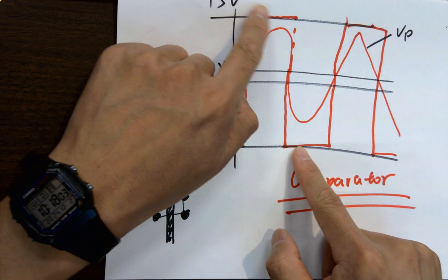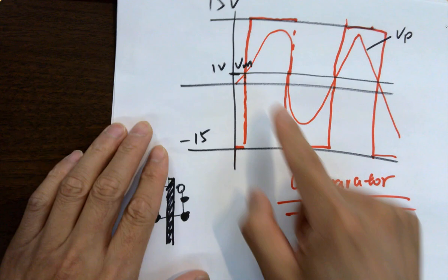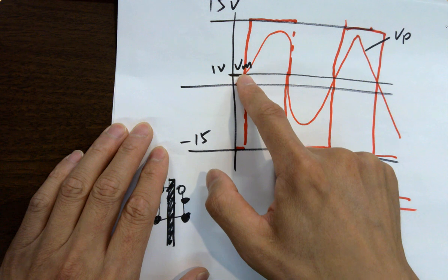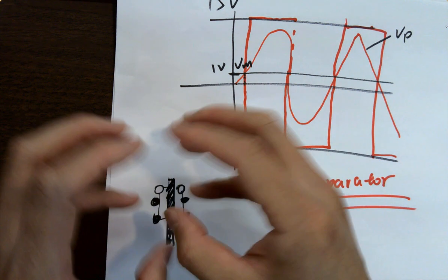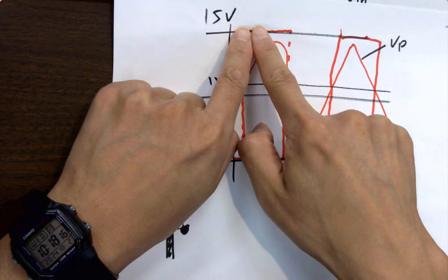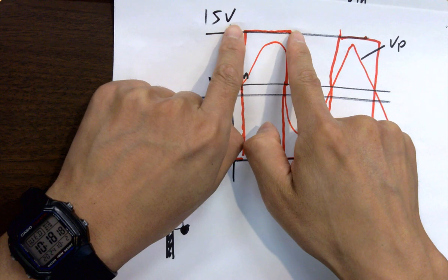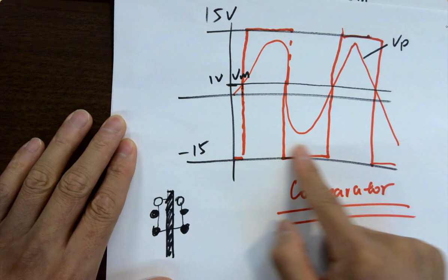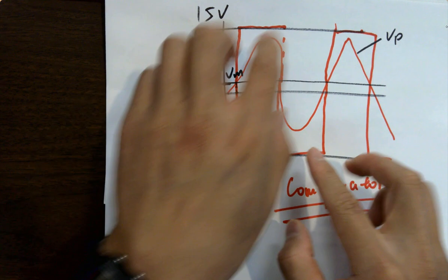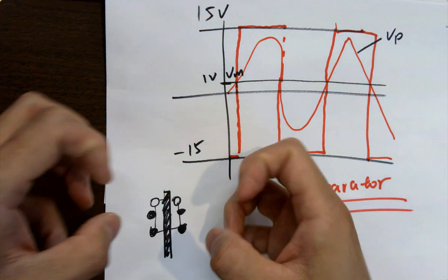So the comparator works super fast because of the huge open loop gain. It's going to respond really quickly whenever there's a little tiny signal change. I'm not drawing the internal circuit over here. It's complicating things. But what I'm telling you is, if you look at the output of the comparator, you'll know that you're turning the motors on and off depending on the signal. So you can use these signals to control the DC motors of the two wheels.